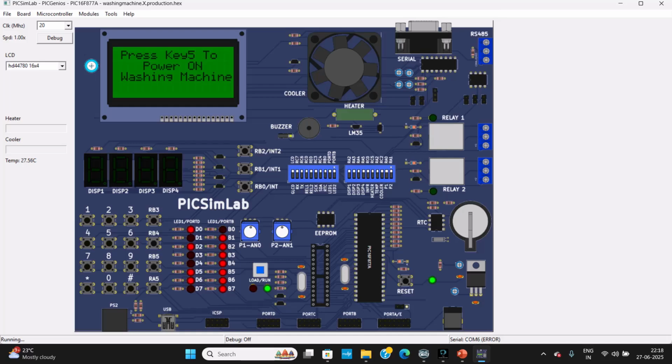We have written the code related to the project in MPLAB X IDE. We wrote the header files and source files for the digital keypad, timers, and the CLCD, and the main.c. After building all the files, the hex file is created, and we have to load that hex file into this microcontroller. We use the setting for the LCD display.